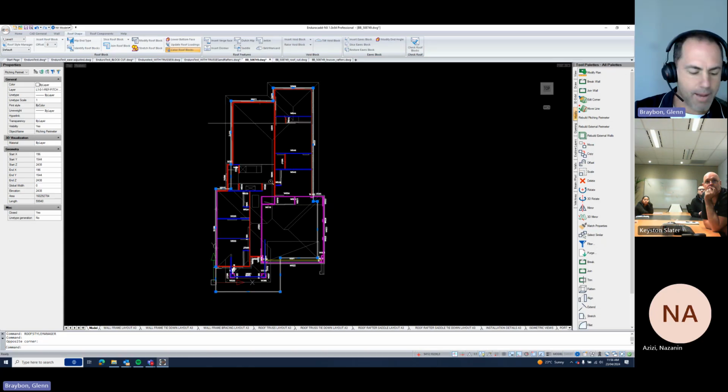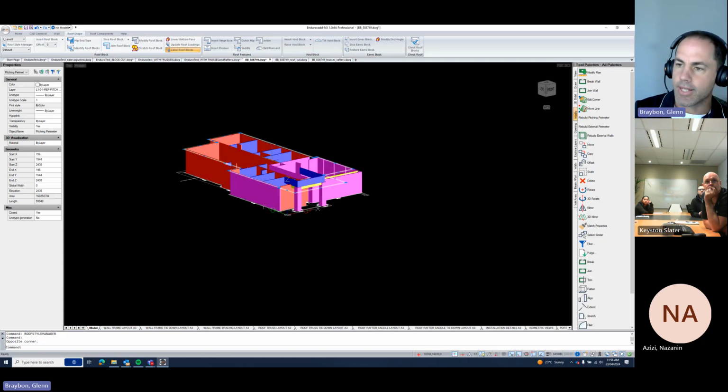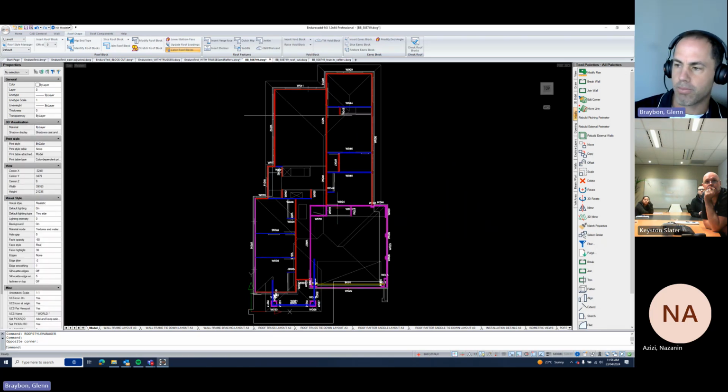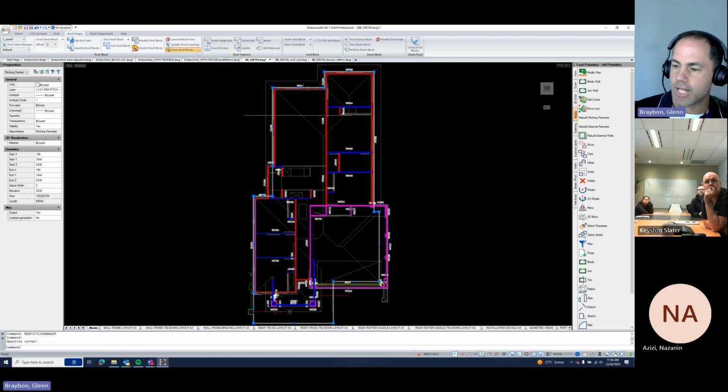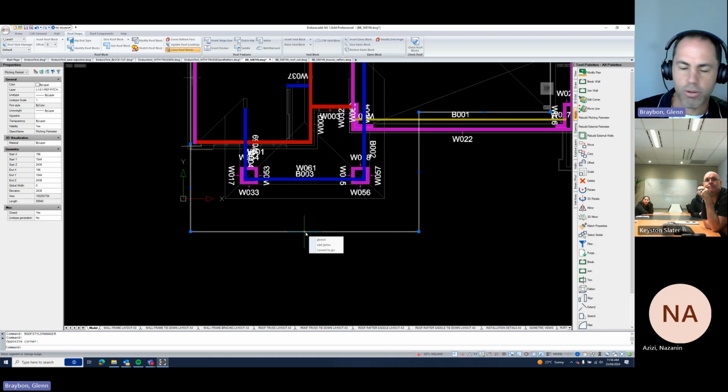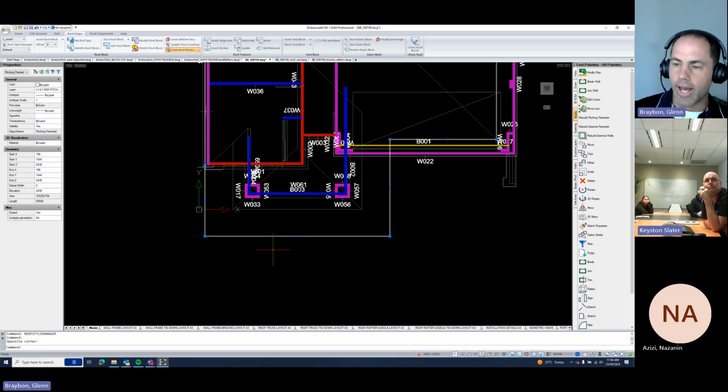So our pitching perimeter now is this white line, similar to a polyline in CAD, and we make changes to it by using the grip points. And you can change that to different colours to suit, can't you? Yeah, absolutely. In the layers menu, your pitching perimeter is on your L1 RF pitching perimeter layer.